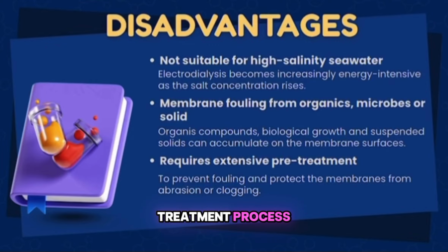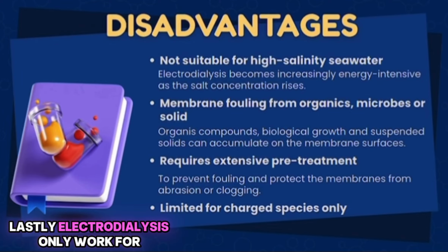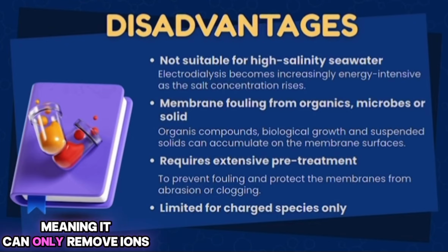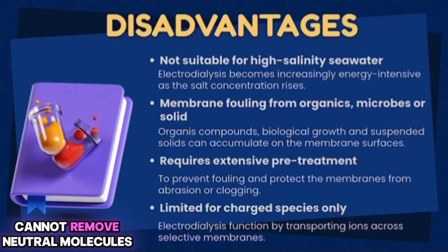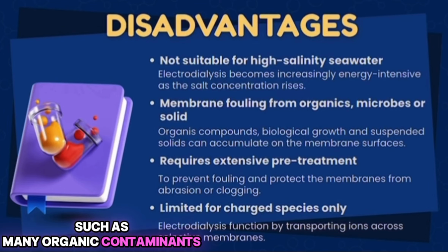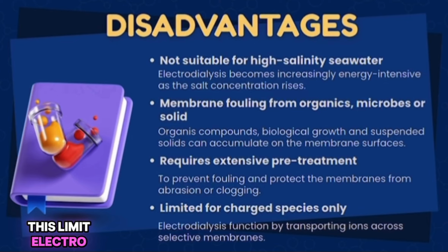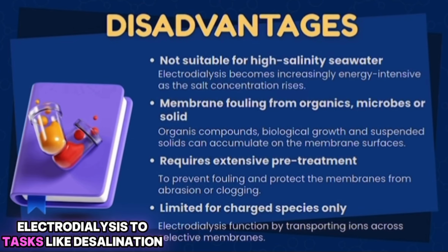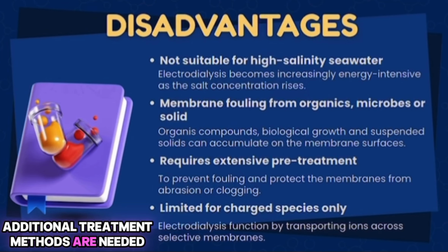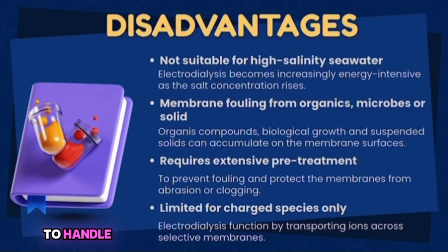Lastly, electrodialysis only works for charged species, meaning it can only remove ions and cannot remove neutral molecules such as many organic contaminants. This limits electrodialysis to tasks like desalination or ion removal, and sometimes additional treatment methods are needed to handle non-ionic pollutants.